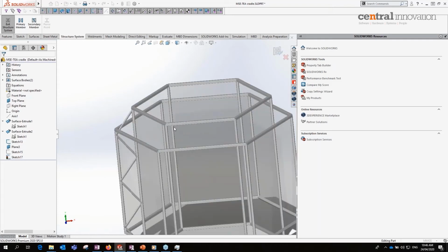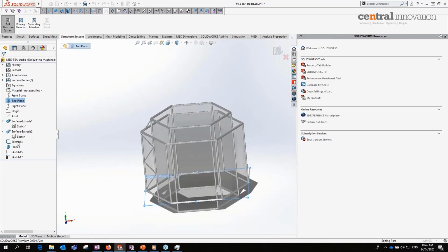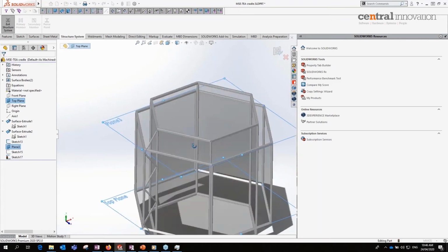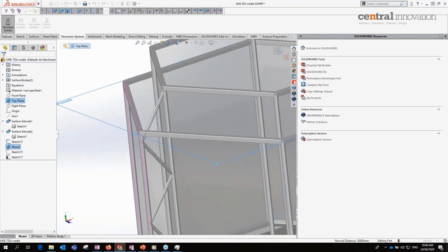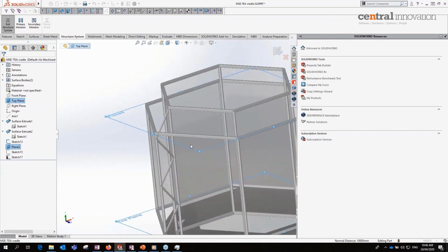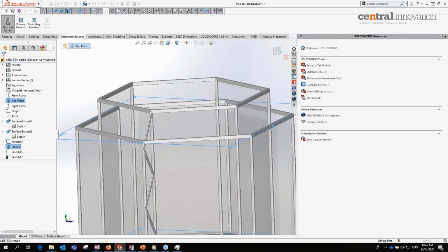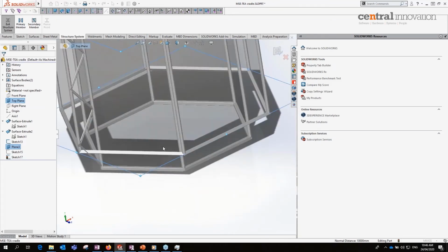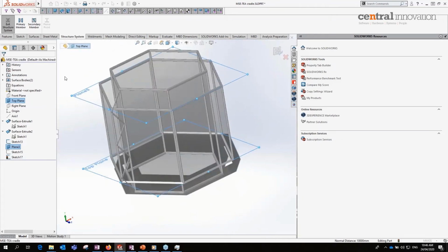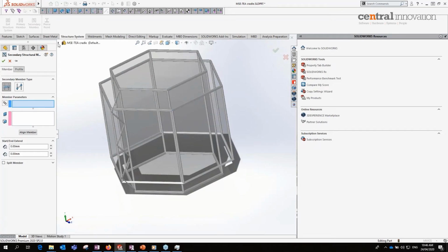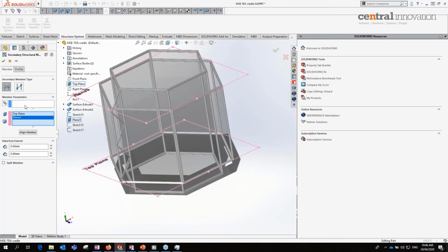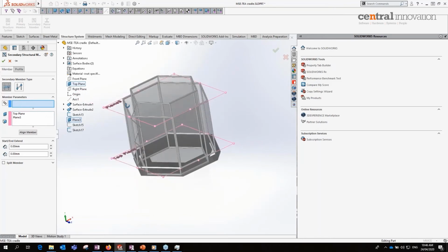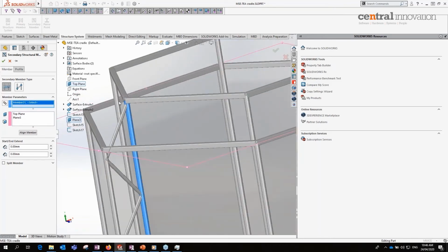another complex one. Like let's say we want to use top plane and this plane to create a member for connecting the vertical tubes together and the intersection with the plane, mainly for the inner structural members, not the outer. The outer already has a connection here. So I'll use the secondary member using top plane, define plane, using top plane and using this plane for all the round members in the inner loop.